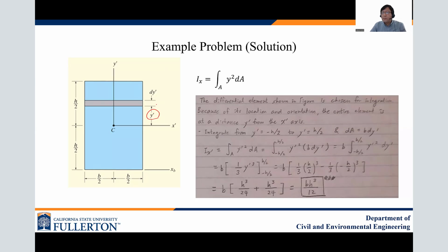To find the moment of inertia for the rectangular area, the differential element shown in the figure is chosen for integration because of its location and orientation. The entire element is at a distance y prime from the x prime axis.